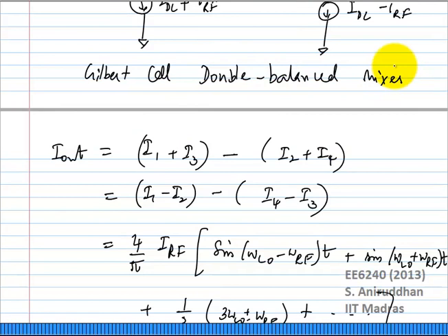Any idea why it's called a Gilbert cell mixer? Gilbert would have patented it. That's an even better way of saying than Gilbert found it. Okay. Yeah, so Barry Gilbert actually used this circuit as a multiplier with bipolar based circuit. And in those days, obviously, multiplication in the analog domain was an important problem. So I was able to build a nice 4-quadrant multiplier using bipolar devices in this particular form. This is the MOS version of the Gilbert cell mixer, of the Gilbert cell. You are using the multiplier as a mixer, as simple as that.